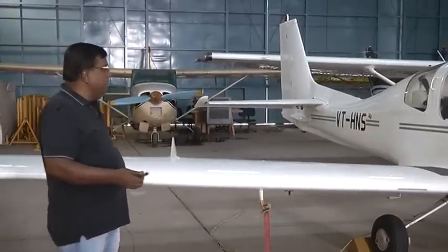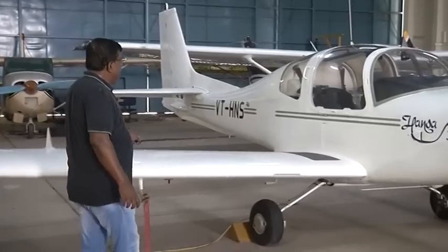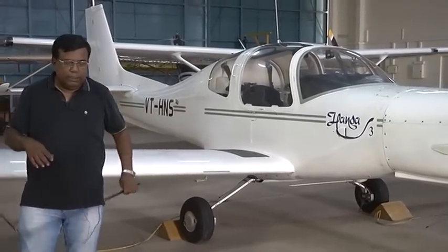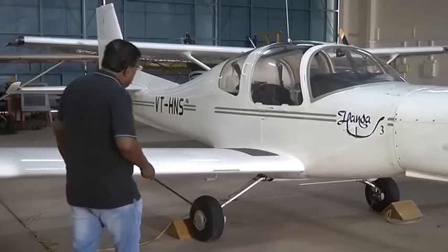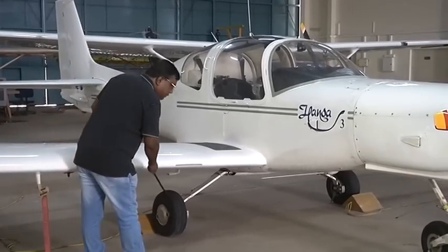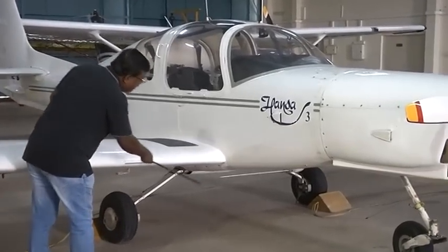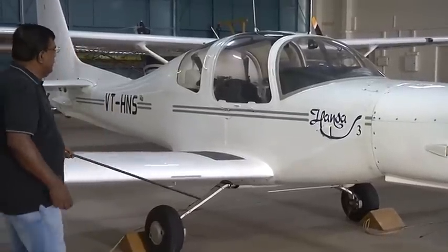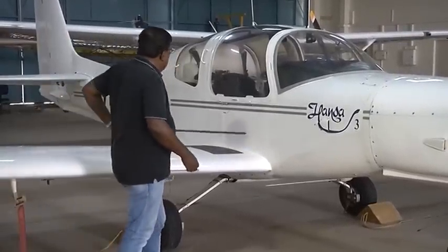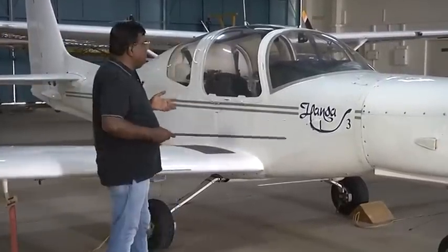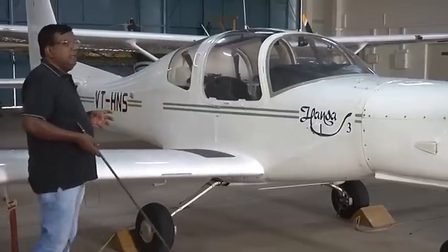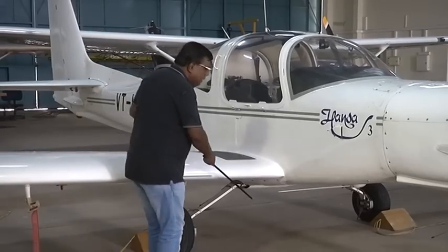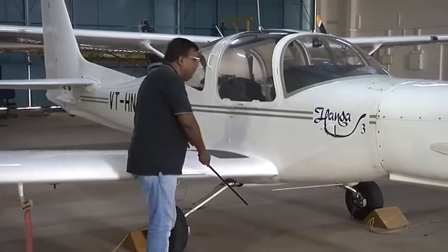So you will not like to keep the CG behind the landing gear, although the CG will be close to the landing gear. That is why, if you see an aircraft, once the landing gear is located, the CG will be somewhere very close to the landing gear, but ahead of it. So we say the CG is somewhere here. And the second part: how do I distribute the mass so that the CG is at the point where I want? One is, okay, I have seen the landing gear, so I'll put it a little ahead of the landing gear.